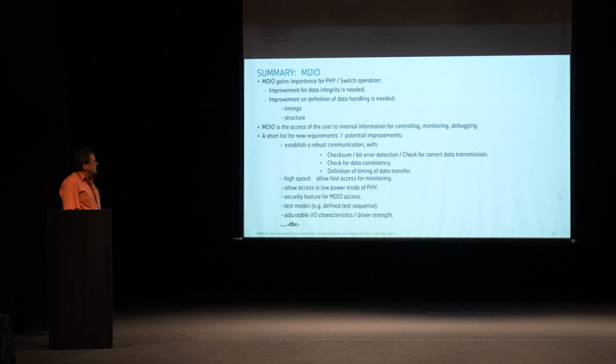We should have some means like checksums, checks for correct data definition, data consistency, and timing. The next topic: we want to get more data out of the device, and it might also be good to have high-speed access, also in low power mode. So MDIO is our view into the chip. And we should have test modes and adjustable IOs, because sometimes you need level shifters in between. The list might be continued, and as I said before, it's a discussion, a starting point for all the people working with PHYs and switches to think about a good solution. It might be different from what I've written there.